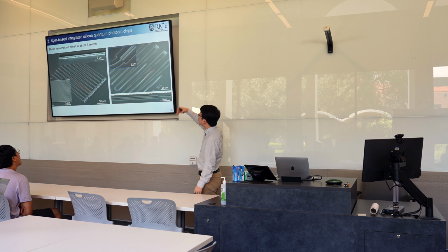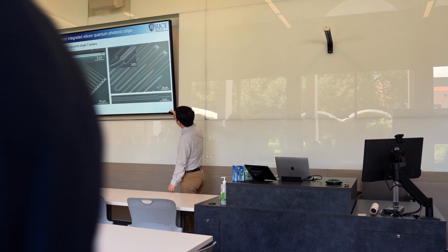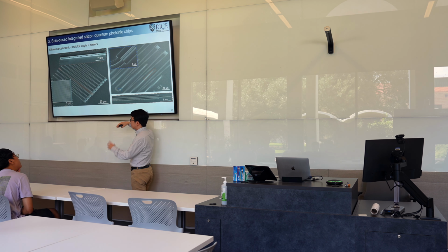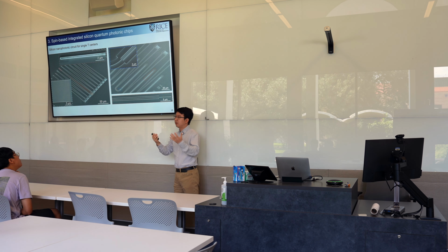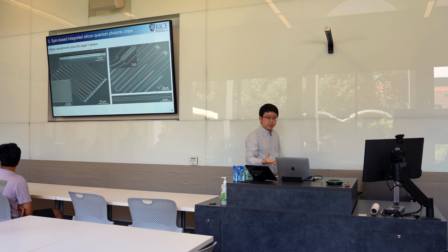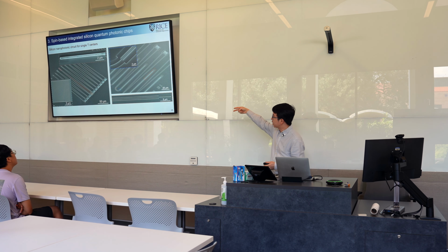Recently, we moved to what we call a second generation of the devices, where instead of one grating coupler coupled to one cavity, now you have an array of cavities coupled to the center bus waveguide in an evanescent way. Okay, so now a single grating coupler can talk with all the cavities on both sides of the bus waveguide, which can be a large number.